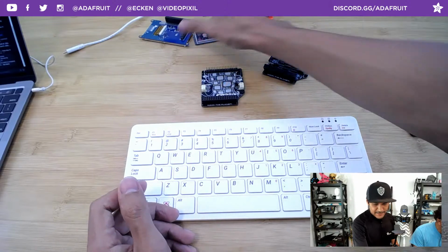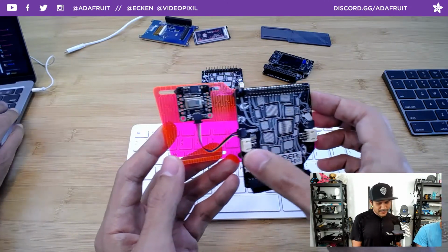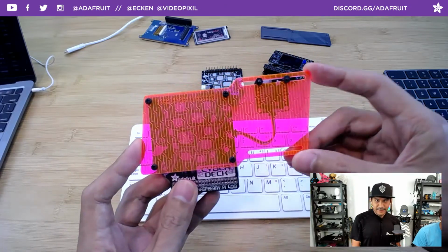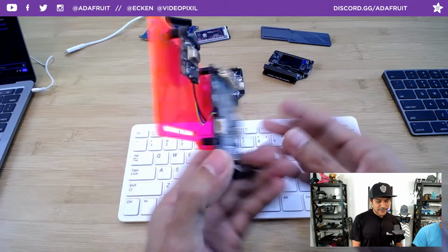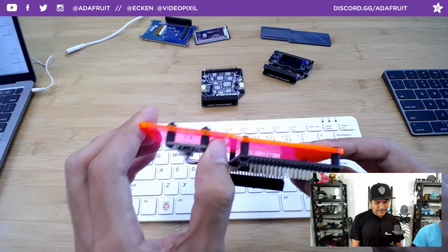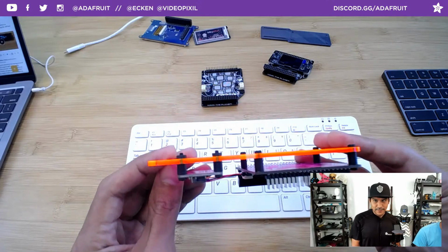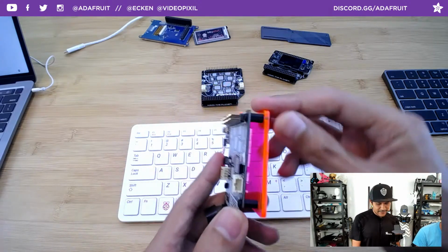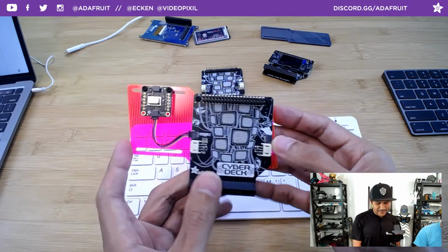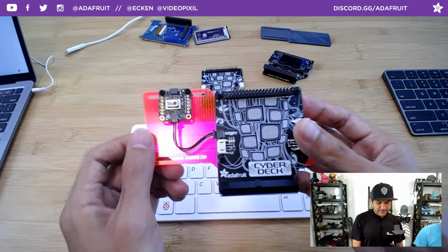And then this is what we did this week. You can 3D print or CNC mill or laser cut this little expansion plate. The expansion plate has these 2 slots, and the slots allow you to secure some of these Stemma QT breakouts to those slots with some hardware. So I got these standoffs. These are M2.5 standoffs. We sell a kit as well, so if folks want to pick that up, you can start using some hardware to attach your stuff.